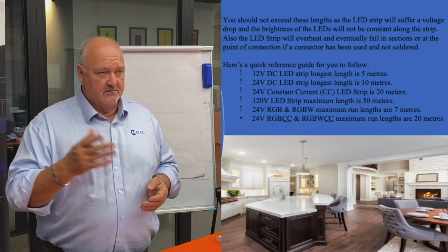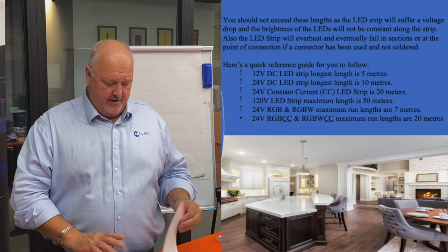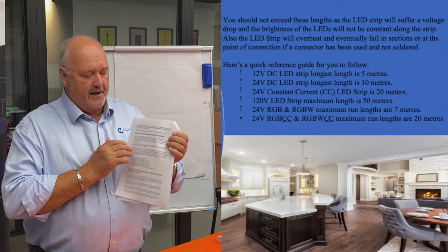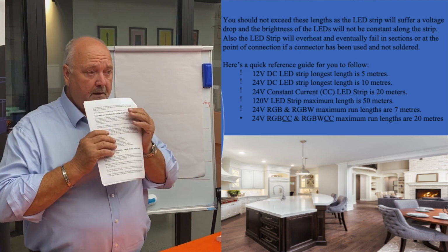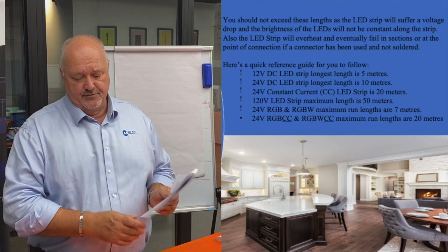So if we're looking at a standard everyday 12 volt DC LED strip, max length is 5 meters. 24 volt, 10 meters, and so on. There is a chart and information here in your paperwork to explain all of that. But no, the controller does not limit the length of the strip.